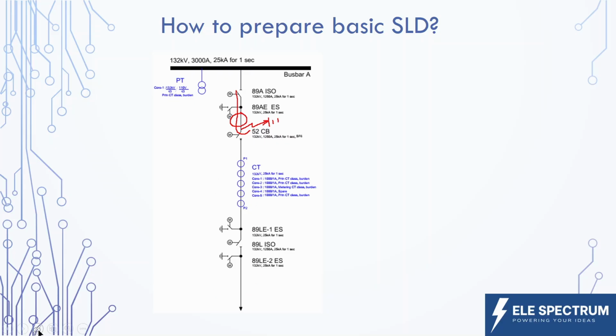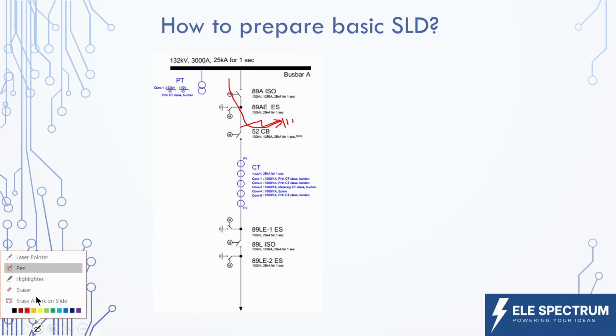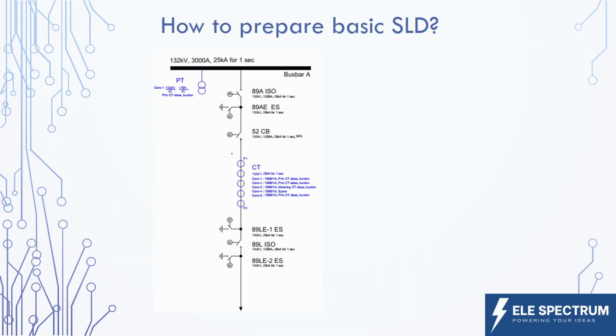So instead, suppose we place the current transformer as we have shown, and we have a fault at the terminal of the circuit breaker on this side. Any current flowing through this part will not be detected by this current transformer and the protection relay, and this circuit breaker will not be tripped. However, this current will be detected by the bus bar protection, and only this circuit breaker will be tripped. So we should be placing the current transformer after the circuit breaker as we have shown here.